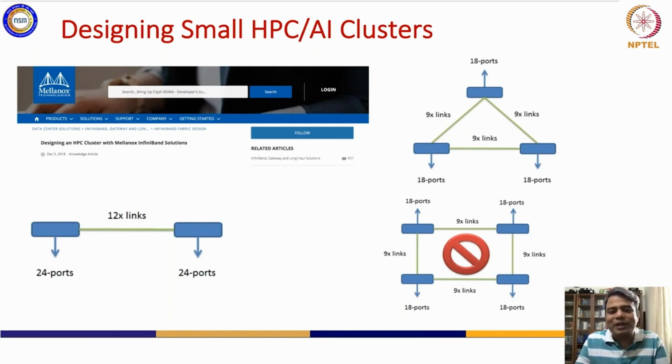How many ports you can take out of that die would depend on how many pins or ball grid arrays you will have from that silicon. It's a very simple way of saying that, okay, I cannot take a 2-inch by 2-inch die, because then my yield is not very high.